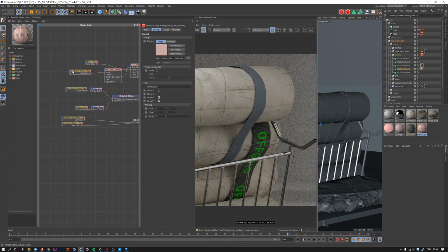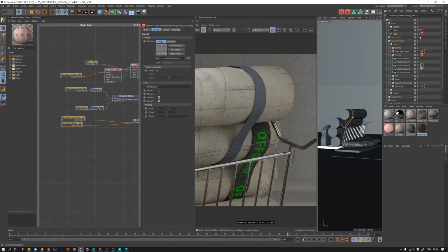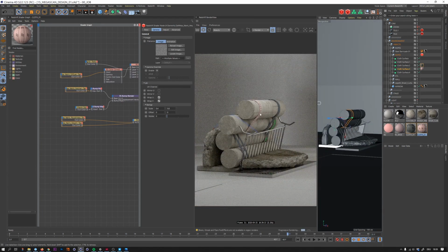So therefore I'm switching to the material and I'm just quickly selecting all of the materials, and I set 0.4 and 0.8, and let's switch back to the main camera and see. Yeah, now we can definitely see that, but for this one I would say we can go a bit smaller, so 0.5 and 1. And yeah, this looks nice. Let's save it. What next?